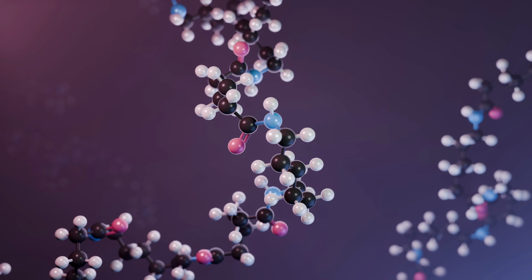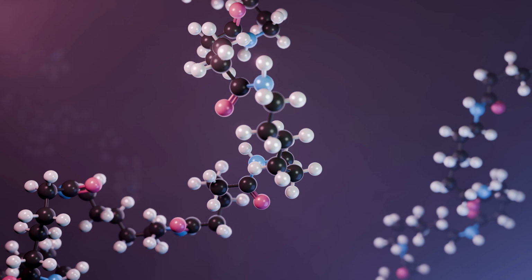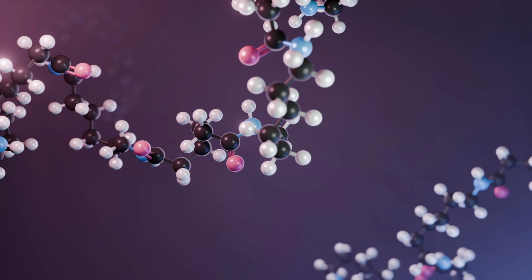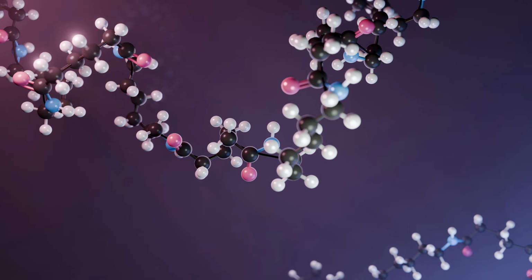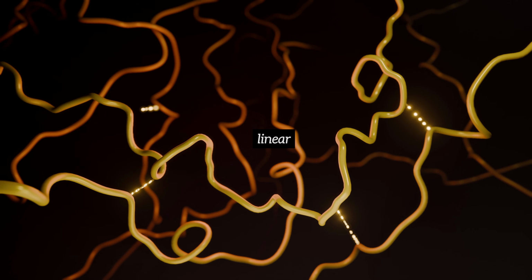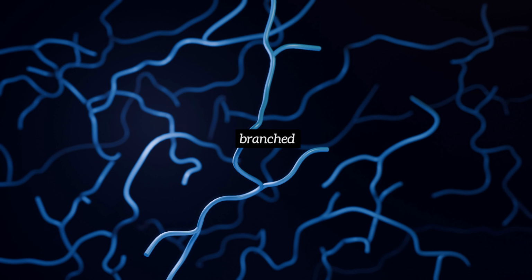Polymers usually have a dominant structure type, depending on the polymerization conditions and the monomer involved. This affects how the polymer chains interact with each other, and plays a key role in determining the polymer's properties. In a linear arrangement, the polymer chains are continuous lines, with each mer in the chain only being connected to two other mers. The chains are held together by relatively weak intermolecular forces. In a branched arrangement, the chains are held together by the same weak intermolecular forces, but the main backbone of each chain can have side chains attached to it.